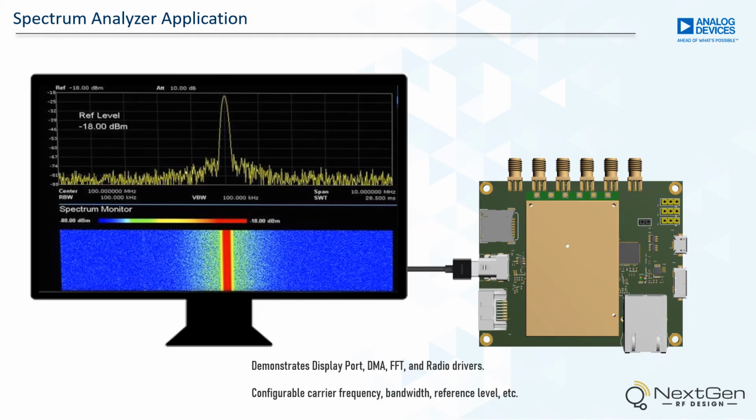Several additional application examples are provided, including the Spectrum Analyzer. This application demonstrates various peripherals, including the ADRV9002, along with FFT signal processing and video processing within the programmable logic.